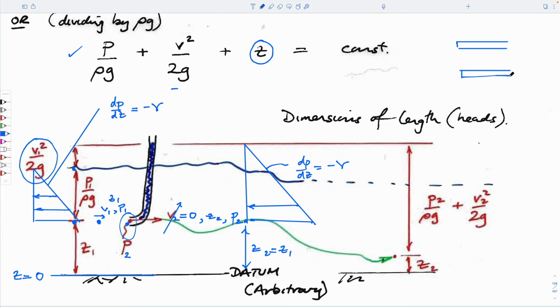So this is the front part of the tube. This in it has stagnant air. So the air is hitting this. It's closed. It goes up here and it goes up here, which is this portion here. This is closed and capped off with a pressure transducer. So there is no flow in here. It's stagnant. I didn't finish the word, but that is stagnant.